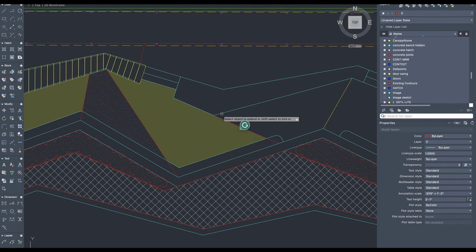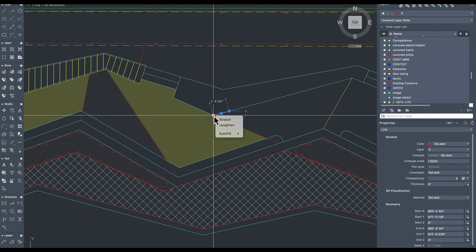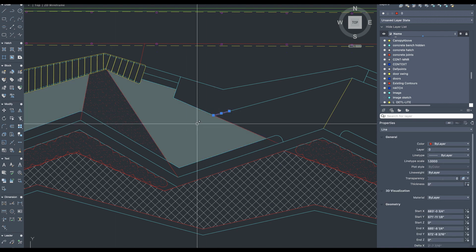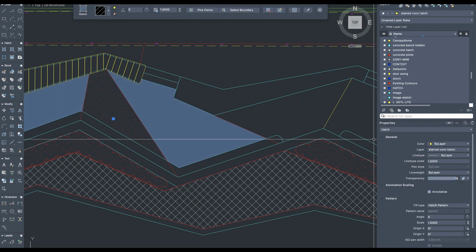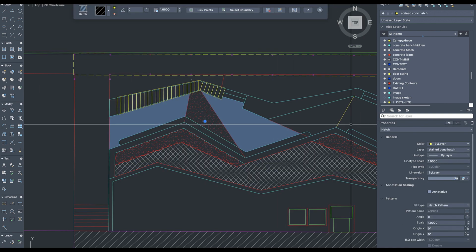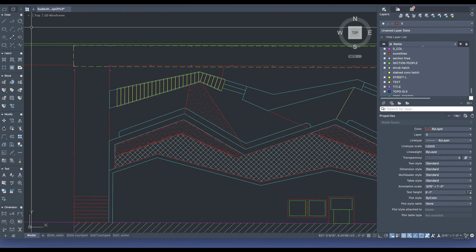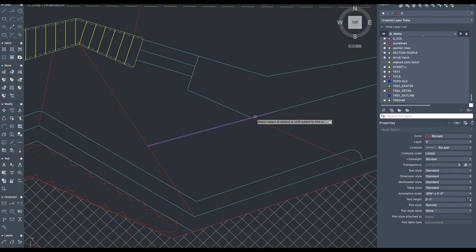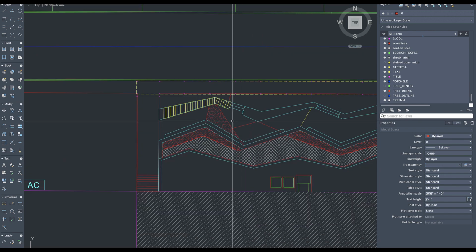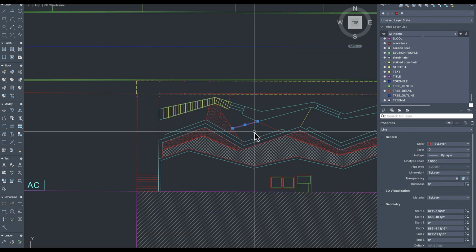So I'm going to click this direction, extend it back across this way, and see if we can get this line to sort of extend out through this hatch, which I might need to turn off. Let's go stained concrete hatch. And EX, extend that line over. That can be another control joint for us, right? So, do I love it? I don't know. Maybe not.